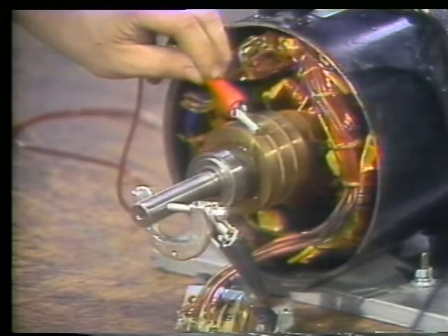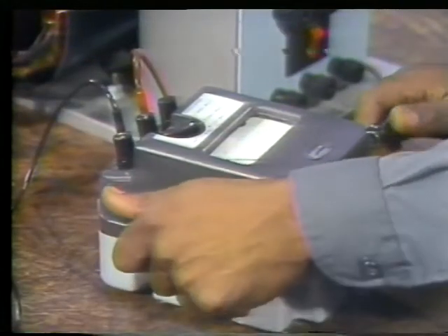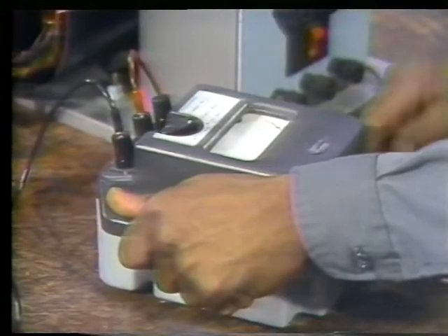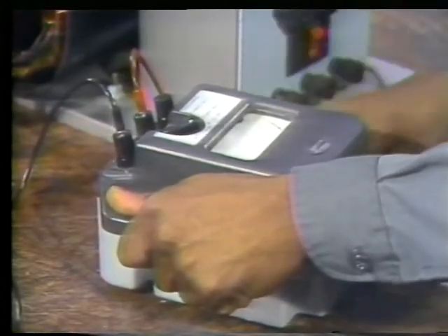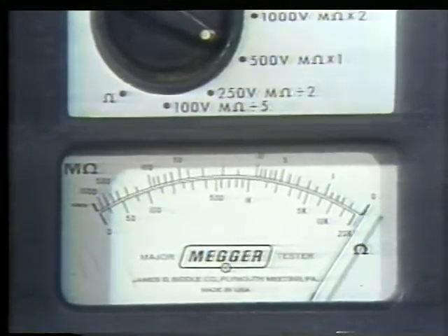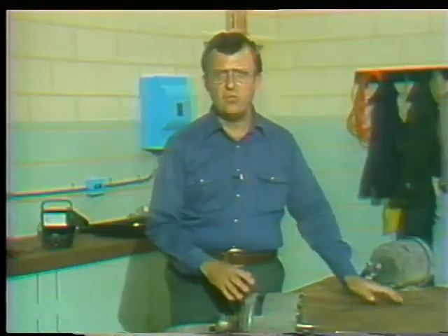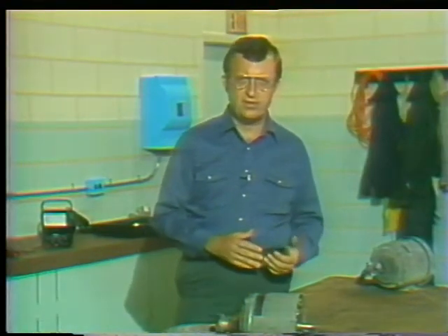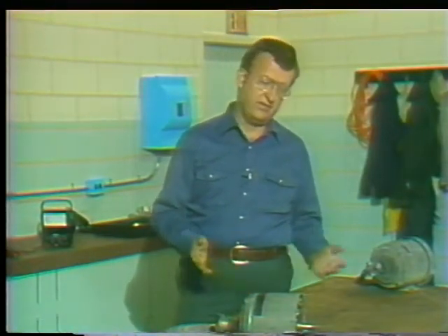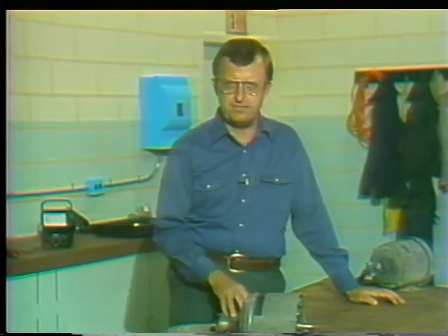Be very careful not to touch the slip rings or the uninsulated portion of the lead with your hands. The Ohm meter could give you a severe shock. If a ground is present in any of the coils, the meter registers less than normal, or perhaps even zero. Once you know there's a ground in the rotor, you might try drying it out, and if that doesn't work, the rotor will have to be removed and repaired.